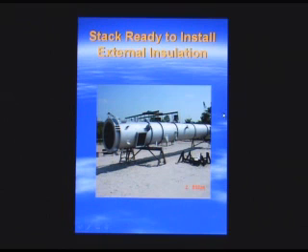This stack does not have what they call strakes, spelled S-T-R-A-K-E-S. They're a means of promoting vortex shedding. They basically break the vortex that could form, which would cause the stack to vibrate. In this case, I believe the stack was of a diameter and height that it was checked and found not to be susceptible to vibration. I take that back. This stack was in two sections. When we get further on, we'll see the stack fully assembled, and we'll see if the strakes are there.